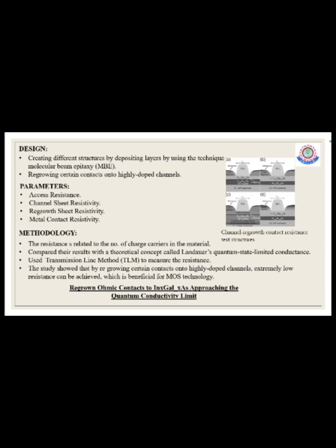And regrown sheet resistivity represents the resistance of the added material that we regrew over the channel. So the resistance of the added material on the top of the channel is called the regrown sheet resistivity. And the last one is metal contact resistivity, which shows the resistance between the metal and the added new material.